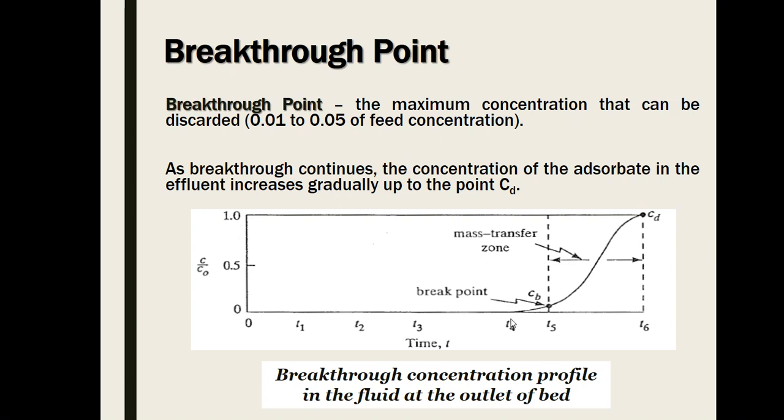concentration. So meaning at the breakpoint, after this, your fluid that was processed in this fixed bed adsorption equipment will only contain around 1% to 5% of the solute, meaning only 1 or 5% of the original amount of the solute that it has. So then it could be discarded.